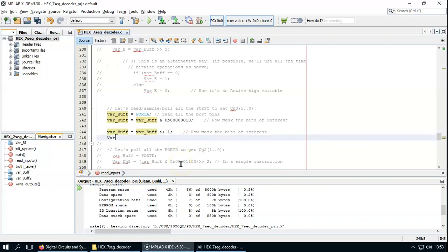It is bar, you see, I don't know now if it goes with capital. Bar BI underscore BI is just the value of bar buffer, right? That's it. So that's the final save operation. You see, read the full bit port, mask the bits of interest, shift to the right position, and save.